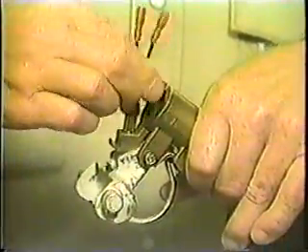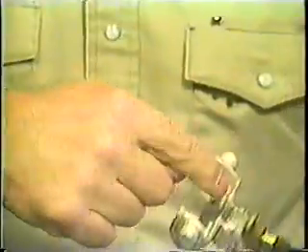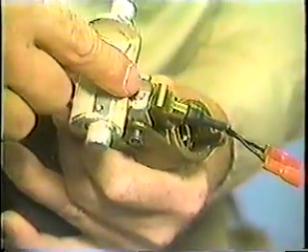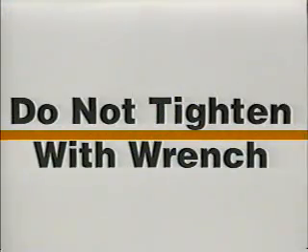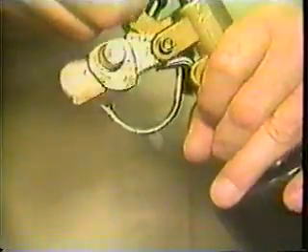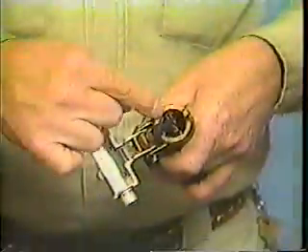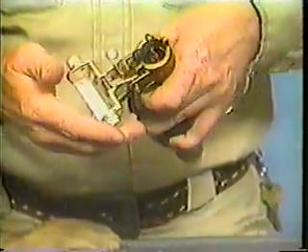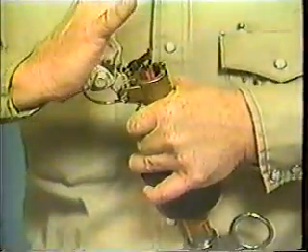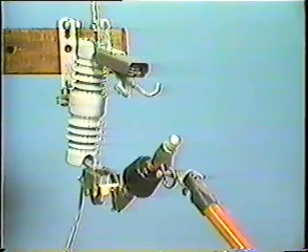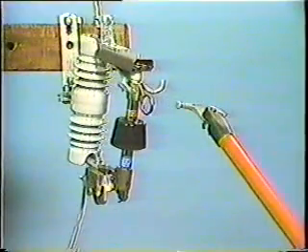Next, install the new actuator in the threaded hole of the lower end fitting and tighten finger tight, making certain the end is flush with the casting surface. Over-tightening may damage the actuator, so do not tighten with a wrench. Place the insulated terminals over the tabs and firmly push them on until they stop. The insulated terminals should cover the tabs. Latch the trunnion in place by rotating it toward the lower fitting. The sectionalizer module is now ready to be returned to service. The used or spent actuator does not require special handling for disposal.